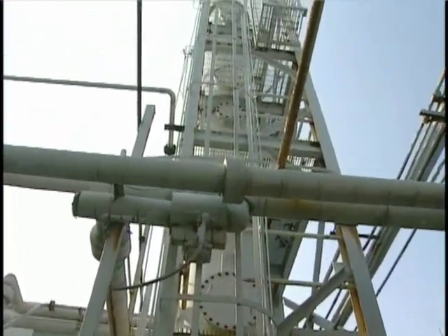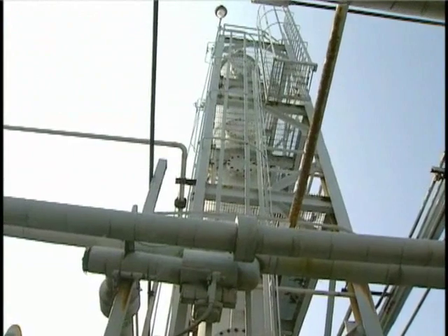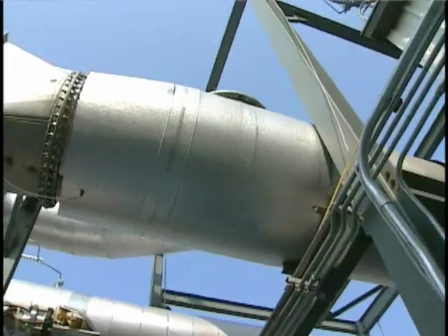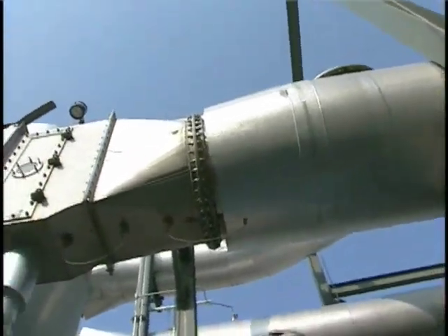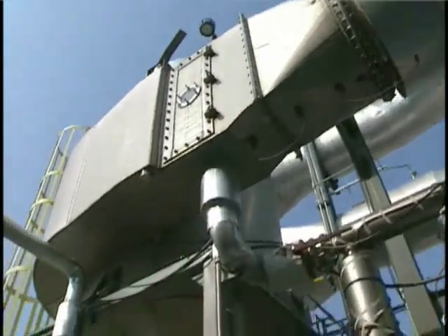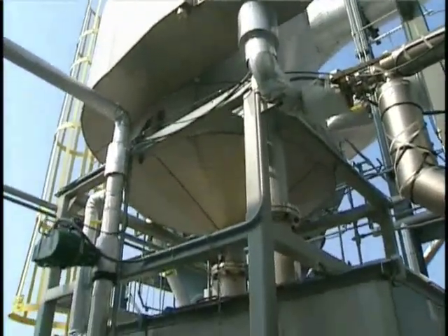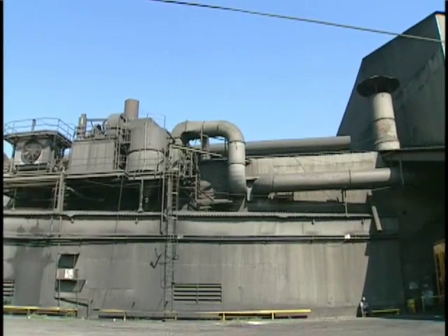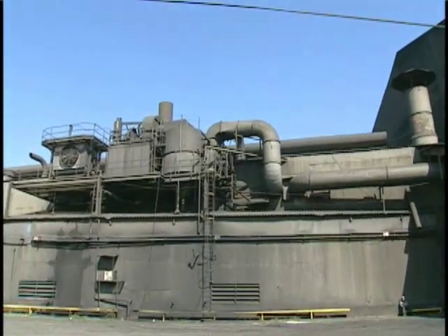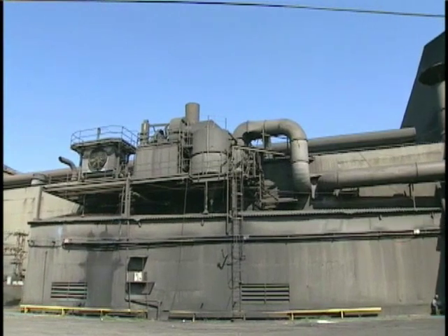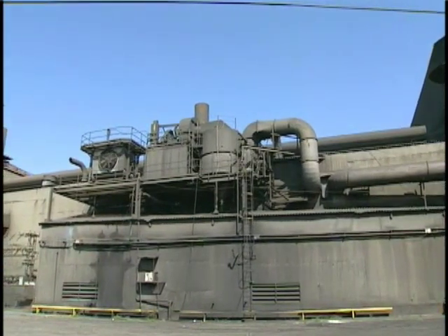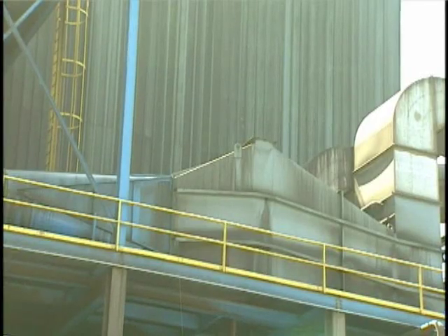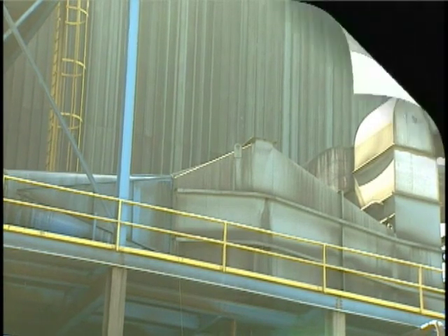Removal of submicrometer particles requires significant energy input, ranging from 25 to over 100 inches of water, depending on the particle size. These collectors are referred to as high-energy wet scrubbers. Not all scrubber designs will conform to these generalized categories. Collectors that may collect smaller particles than their pressure drop would suggest include electrostatically enhanced scrubbers and condensation growth scrubbers.